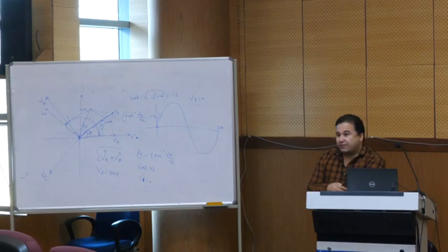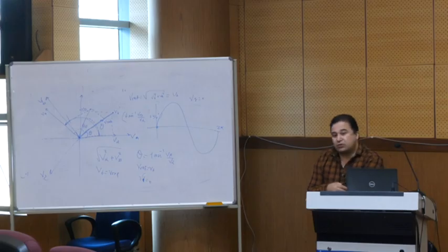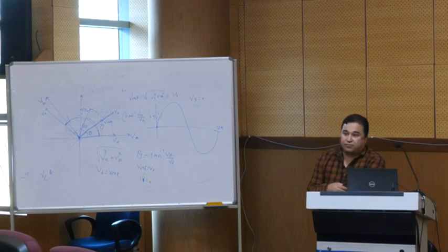But Park, they have the coupling part. So the weakness of Park in comparison with Clarke is that in Park transformation, when you go to the control of the converter, the coupling will appear, but in Clarke you don't have it. But there are also some weaknesses in Clarke.